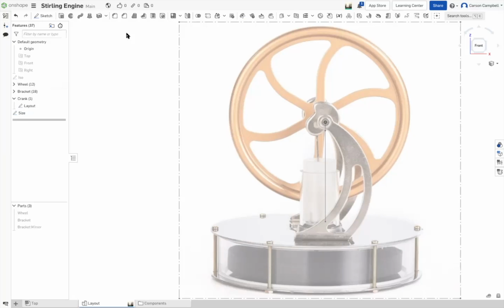That means we're going to have to specify the hole diameter in the flywheel to be 2.95. That means you're going to have an interference. Our shaft cannot be less than 3, can be greater than 0.05. And then the brackets, we're going to stamp that out. Those will probably be clearance holes.